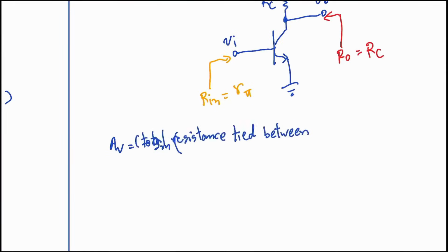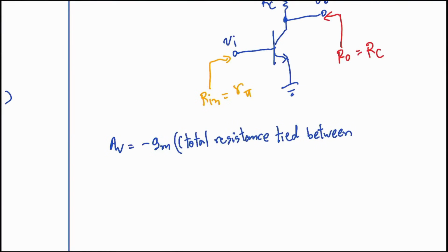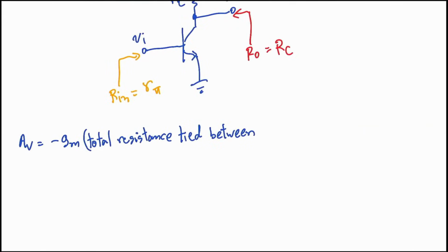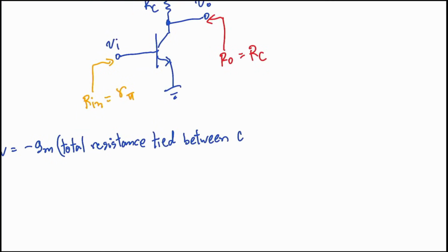So this calculation will ultimately be equal to the total resistance of the circuit. To be more precise, this value will be equal to the total resistance measured specifically between the collector node and the AC ground reference point. It is important to remember that while we are focusing on the AC ground here, the AC ground and the DC ground are often treated as the same potential in many circuit diagrams, though they serve distinct purposes in our analysis of the signal path and the overall stability of the system. These are the same point, meaning they are both ground.